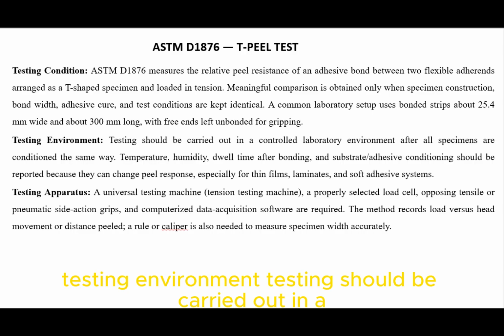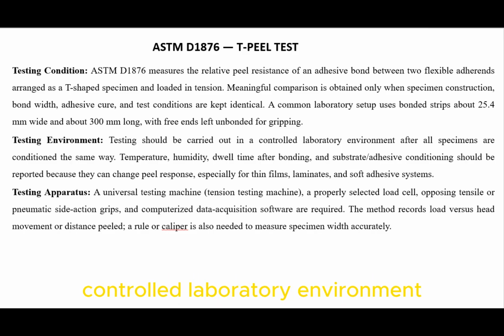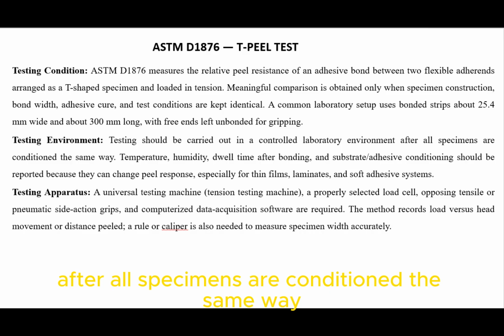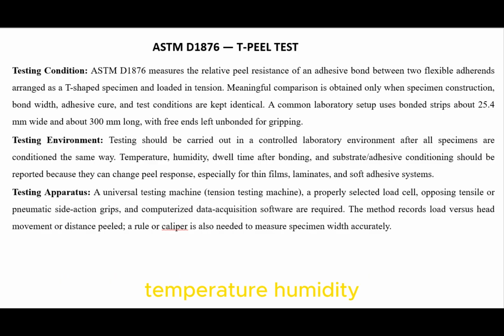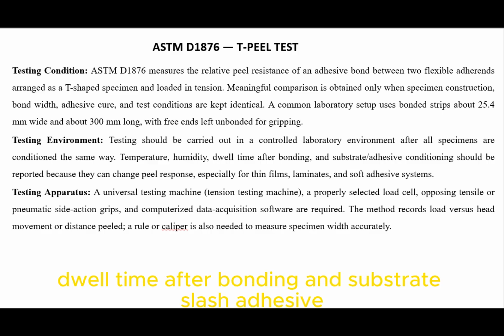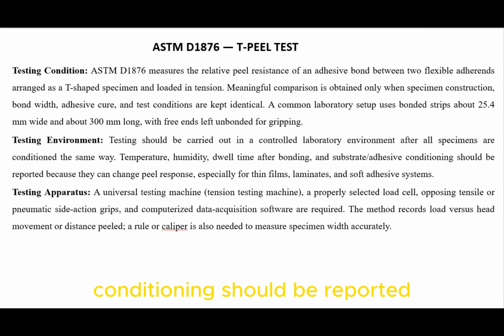Testing environment. Testing should be carried out in a controlled laboratory environment after all specimens are conditioned the same way. Temperature, humidity, dwell time after bonding, and substrate/adhesive conditioning should be reported because they can change peel response, especially for thin films, laminates, and soft adhesive systems.